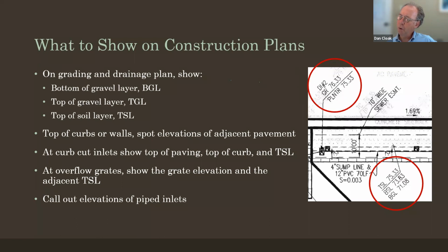Same here with the grade elevation, obviously a key elevation where the overflow is. And you can look right here and say, okay, in this particular case, this was where a 1 foot reservoir was required. In North Bay counties, this would always be 6 inches or half a foot. But the difference between these two numbers is key. And here, you can see you've got your 18 inches of soil and your foot of gravel underneath.